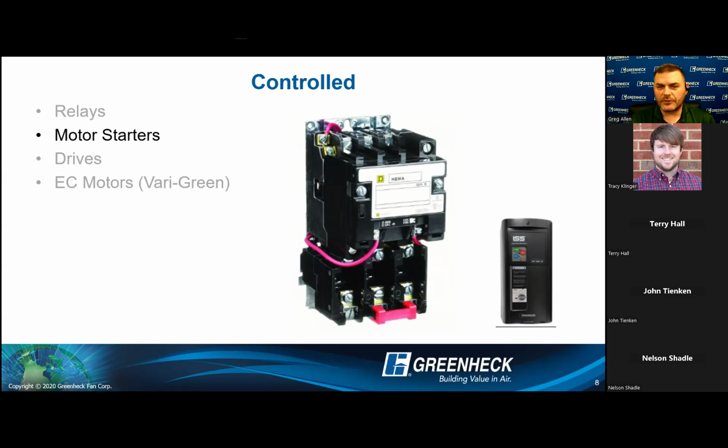Well, and then also motor starters have protection. That's a big part of their job, to look at the amp draw and make sure that that motor is running healthy and to turn it off before you have a really bad day. But in the end here, all the way back to that first big slide, controller and controlled. Am I sending the right signal to this motor starter for it to engage the motor or not?